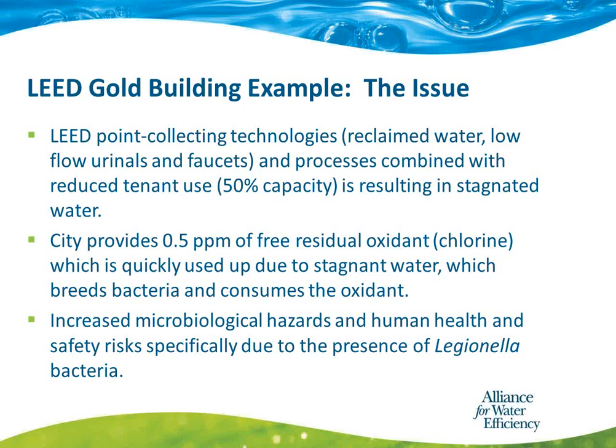So look at this example, a LEED Gold building. There were water-saving technologies involving reclaimed water, low flow urinals and faucets, and processes combined with reduced tenant use, 50% capacity in this building. And this resulted in stagnated water. The water age in the facility was much higher than anticipated.